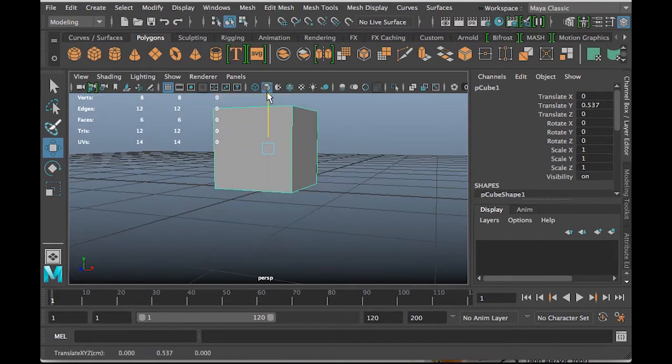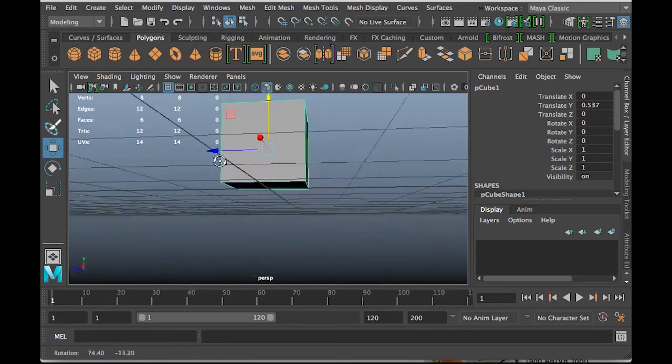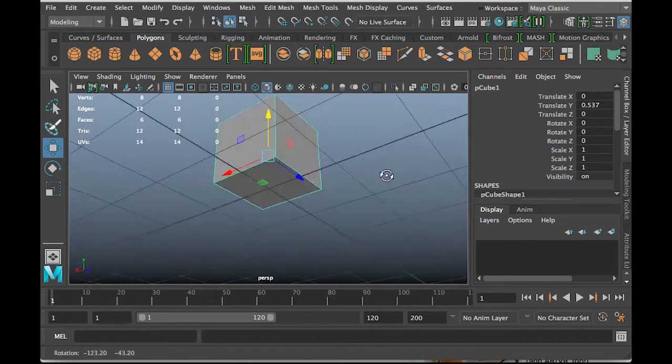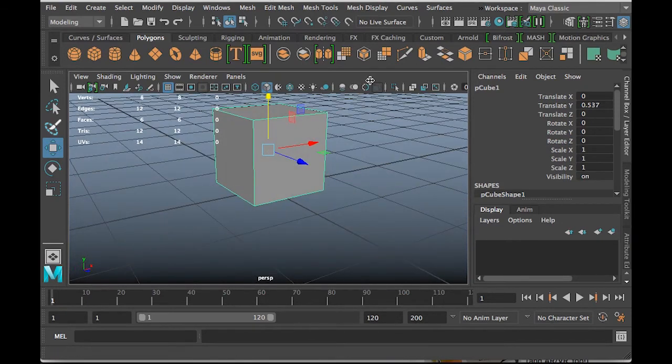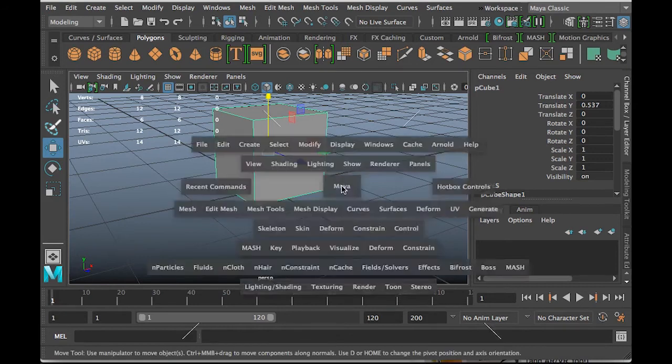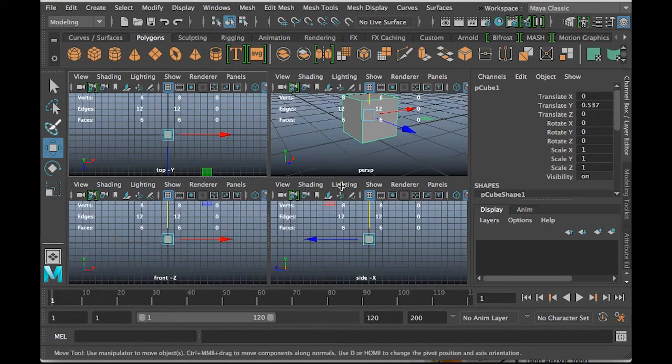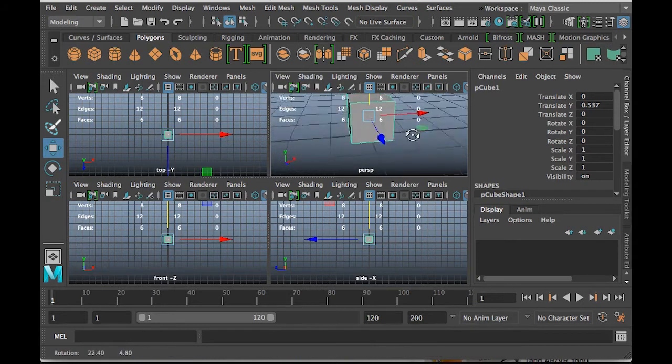Now notice if I do it here, it's very hard for me to understand if I'm exact or not precise. Now comes a bit more tricky. If I press space bar, I split my screen into 4 views. When I clicked on this layout of 4 screens, the first one is the perspective where we worked in, and each one has its own menu, so I can change how it looks inside each screen. With the Alt, I rotate, like I said before.